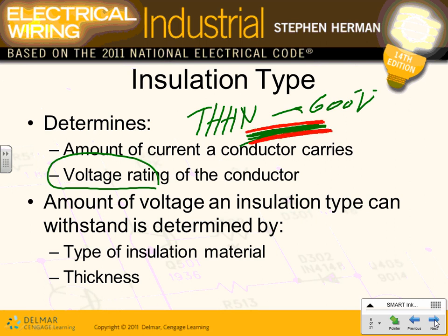Okay, so typically, my friends, the insulation decides the voltage, the conductive material decides the current. But of course, they both play a role. Thicker insulation can trap the heat, so then it doesn't carry more current. The problem with the insulation, guys, is that it insulates the voltage from going somewhere, but at the same time, it traps the heat. If you trap the heat, the best conductor, by the way, is the one that's hanging up in the air, outside, right? No insulation in there, cooled by the air. That will carry more current.